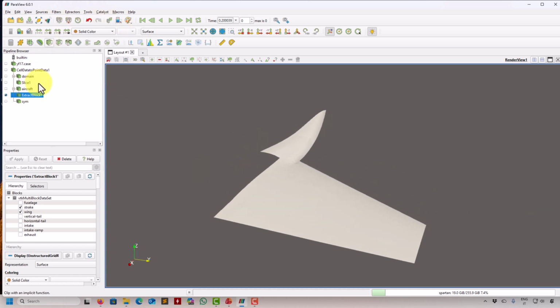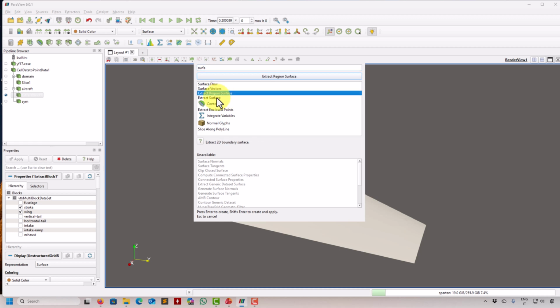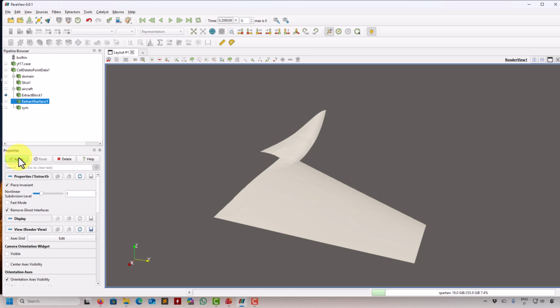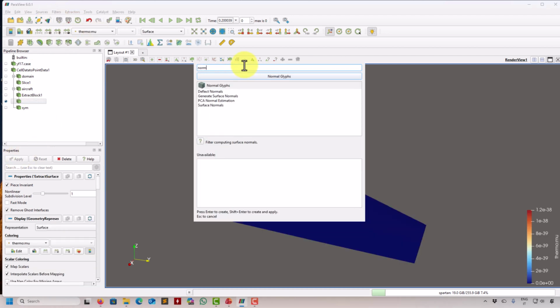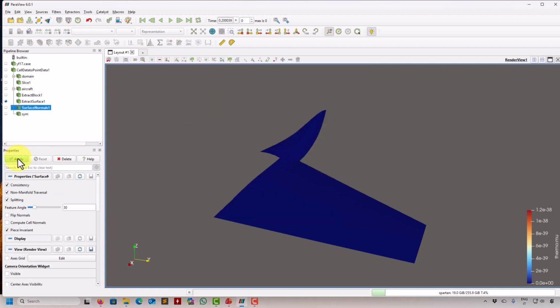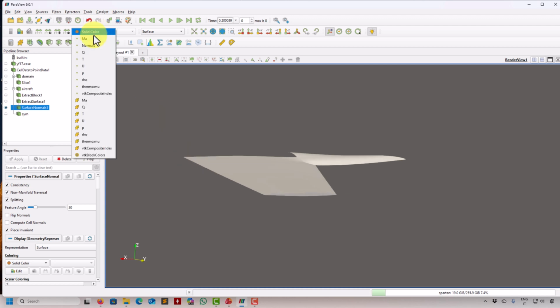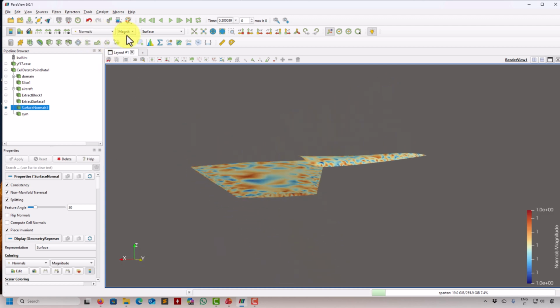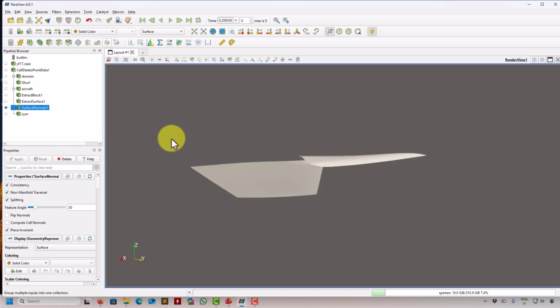I want to create the surface normals. Remember that previously we had that problem, so we need to use extract surface. This time we have it. Sometimes you don't get that problem, so you know the solution. Apply there, and now that we have this one, we can get surface normals, and we are all set. See that we have the normals there. Perfect. So you have your vector, your components, so no issue, easy peasy.